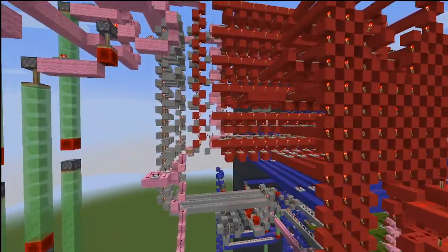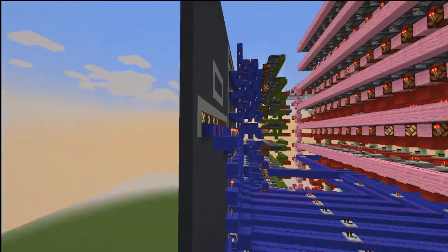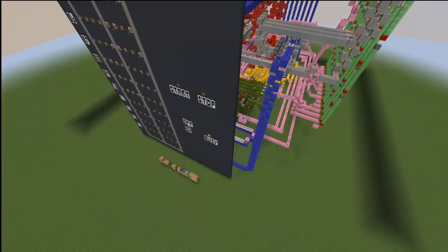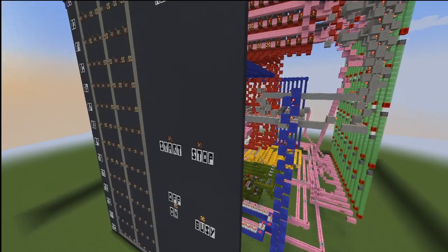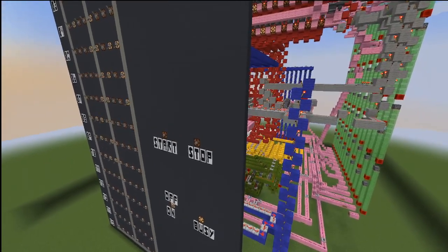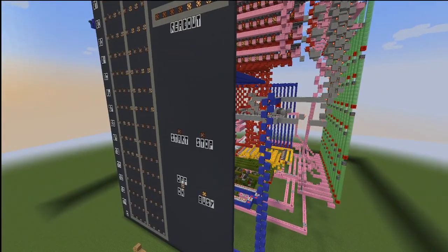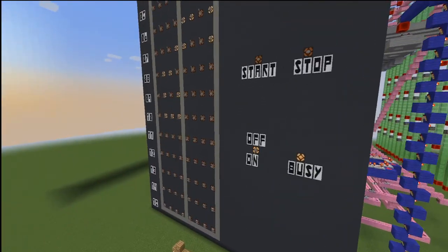And let's see if I can run faster than the lines can carry. No, I cannot. So it put the readout here, but you'll see the busy light is still on. That's because the clock hasn't stopped yet. So that's it for the out macro instruction. It's another short macro instruction, so we're going to have to wait a few clock cycles before starting the next macro instruction, which, as you saw, we had a 10 in the program counter.